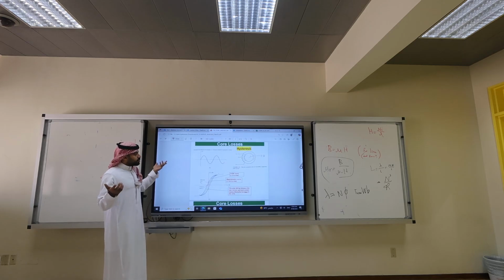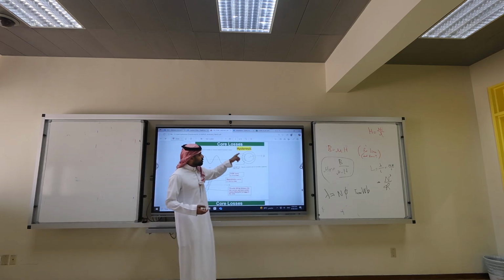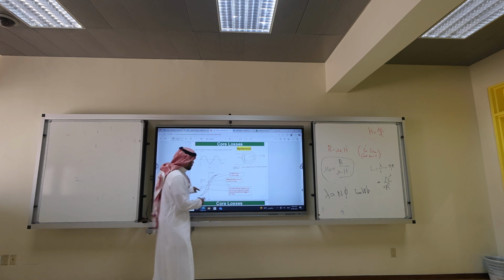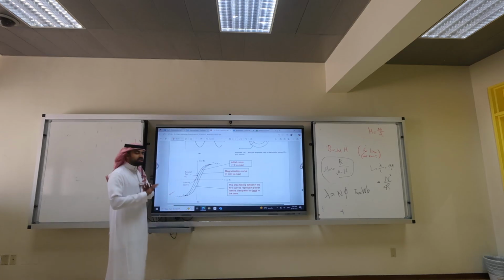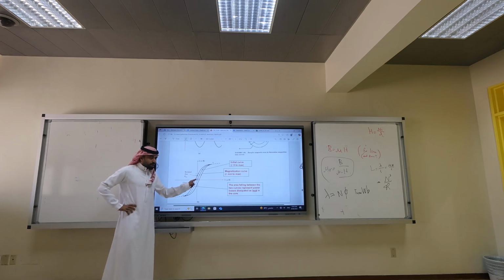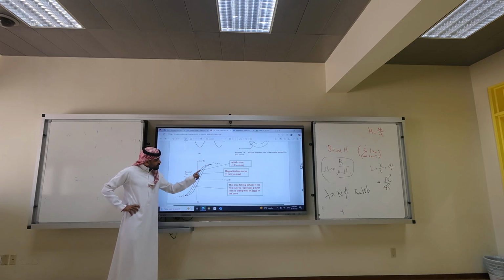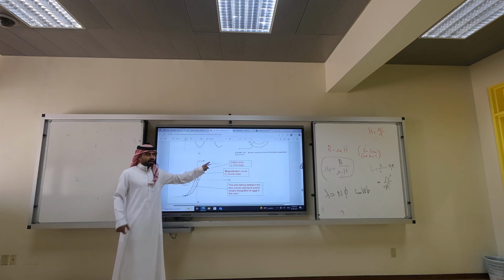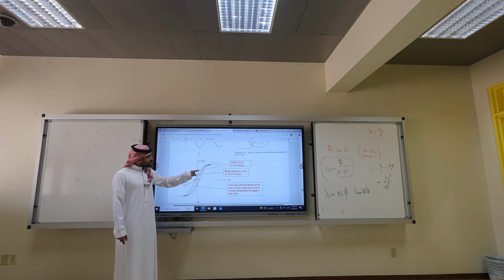What is hysteresis? If I have a core, circle or rectangle, and I send a current, a flux would go, right? If I start from 0 at point A, if I increase the current, would the flux or flux density increase? Yeah. Maybe I increase here until I reach the knee. Okay, now I'm backing up, applying a negative current or reducing I, up until I reach I to be 0.